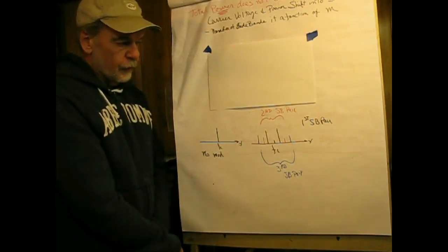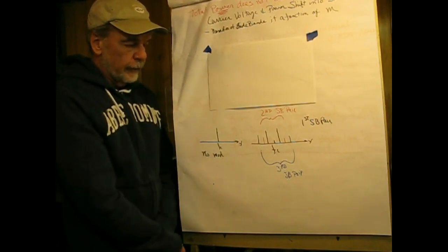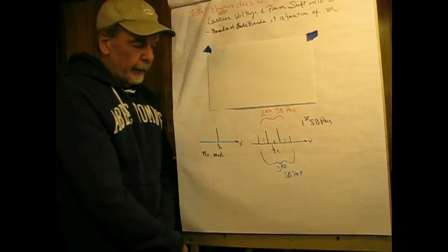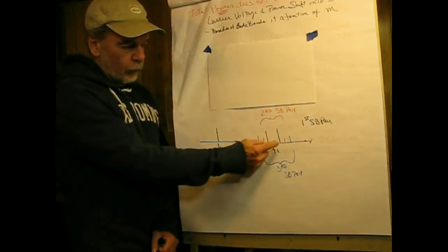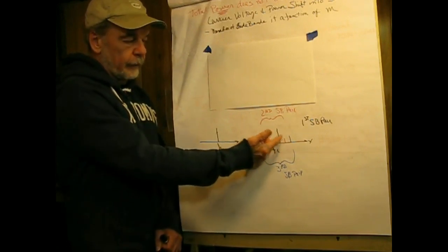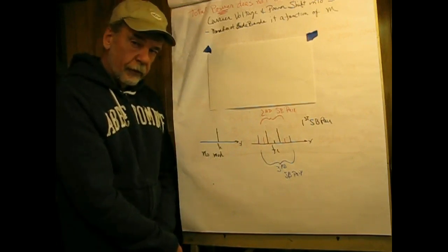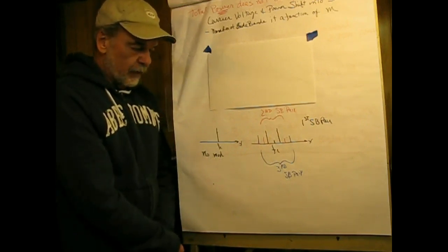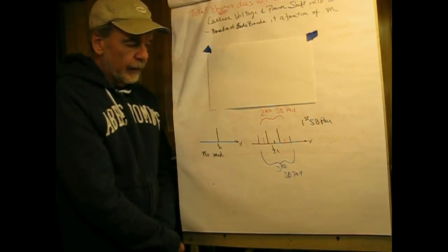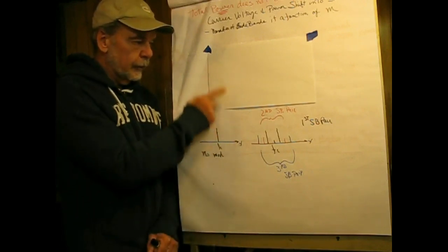So we've got a different situation here than in AM, in that as we apply a modulating voltage, we see these sideband pairs appear, and then if I were to increase the modulating voltage, the first sideband pair may shrink, the carrier may grow, the second may grow, in accord with what's called the Bessel functions. Now, Bessel functions are relatively complicated mathematically, but they're broken down in tables for us that should make sense. So we're going to take a look at those next.